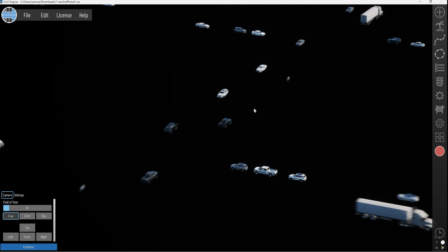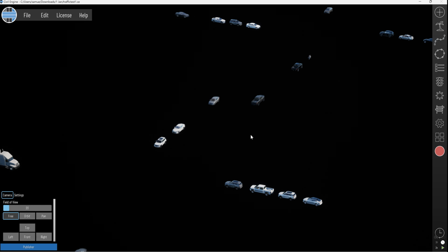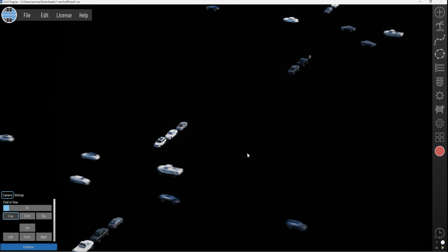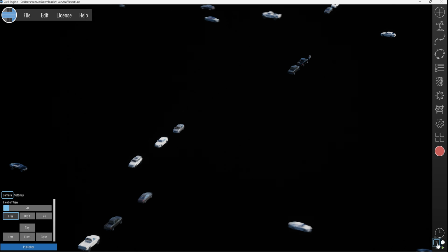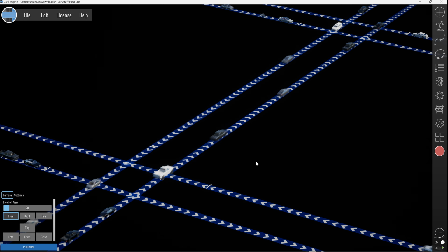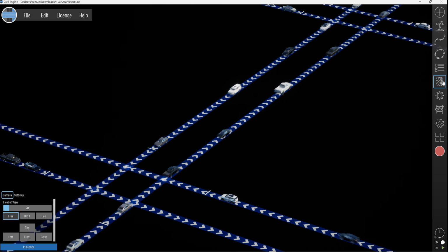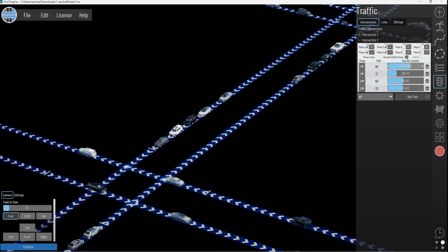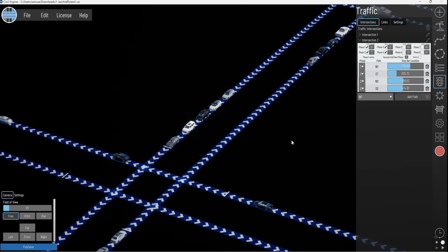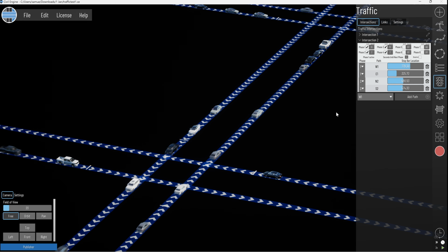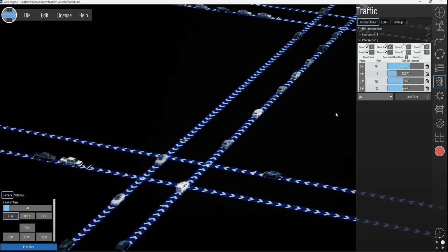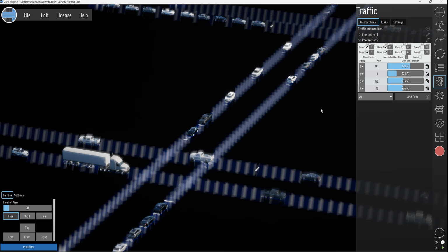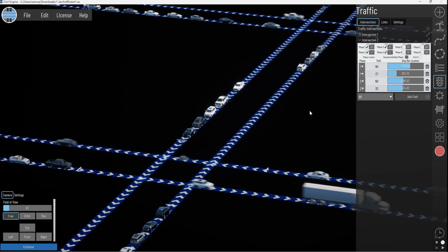All right, I want to show this other one. This is built in a blank scene as well, just to show how you can theoretically use multiple intersection controllers on the same paths. And the reason that works is because each intersection controller, we have 2 here, you're going to set a separate stop bar even though it's on the same path. The caveat I'm giving here, again, this is beta, and so sometimes this doesn't work, and you may end up with bugs where it's not working the way you want it to.